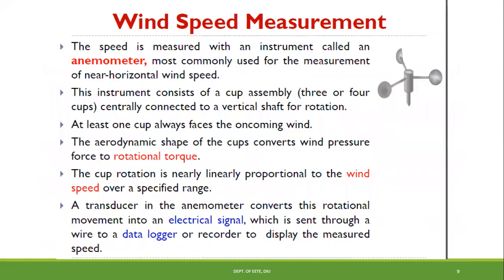The two main important things are wind speed and wind direction, because we know that the wind speed is not fixed and the wind direction is also not fixed. So we need to identify what the wind speed is right now, and accordingly adjust the wind turbine. There is an anemometer, this cup structure. This structure rotates. You can see this type of structure at the weather department of a country, rotating to find out the current wind speed. This is known as an anemometer.